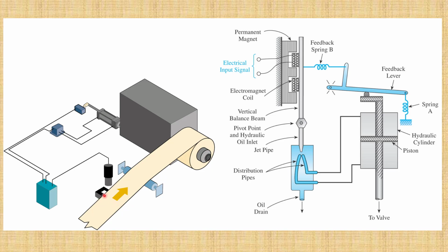So the way this is set up is I have a photoelectric cell here and a light source underneath the strip. And I calibrate this thing so that when the strip is halfway blocking this detector, I get 0 volts.